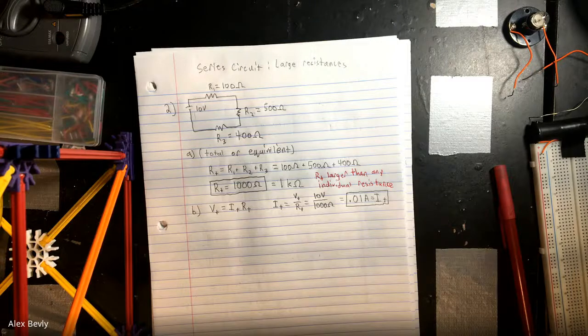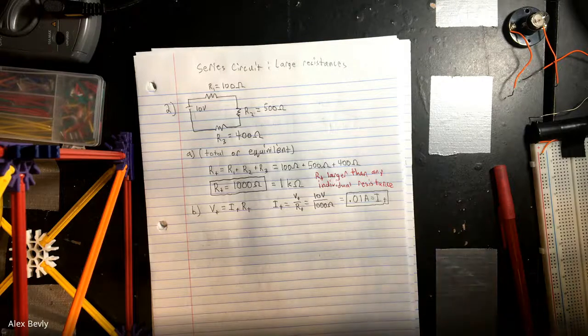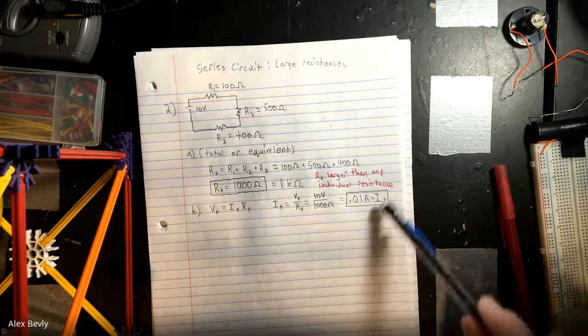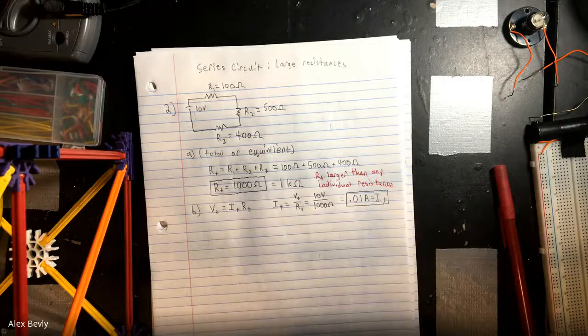But if you're looking at an electrical device and it's talking about something with multiple amps in it, I would not mess with it too much, especially if it's in the tens. You probably shouldn't have anything in the hundreds of amps in your house unless you're dealing with the main electrical supply. These are not things to play around with. And it is the current that actually harms you. It's not the voltage. The voltage is just the thing trying to push the charge through your body. It's ultimately how much of that charge actually goes through your body that's harmful.